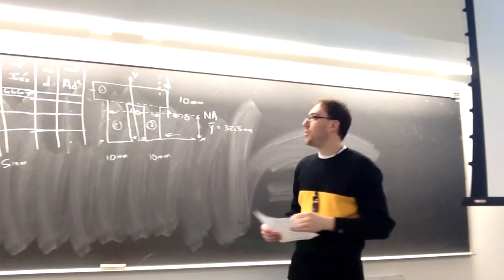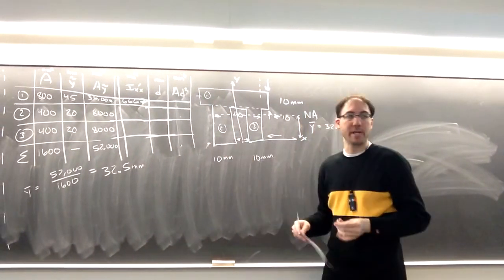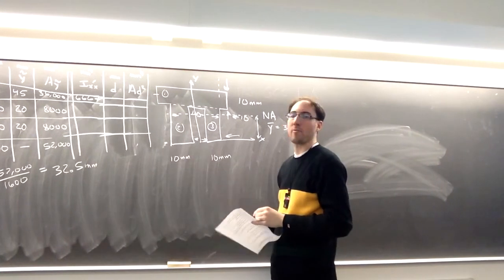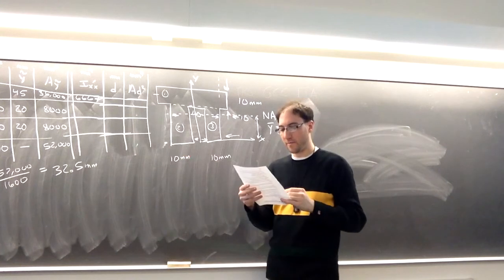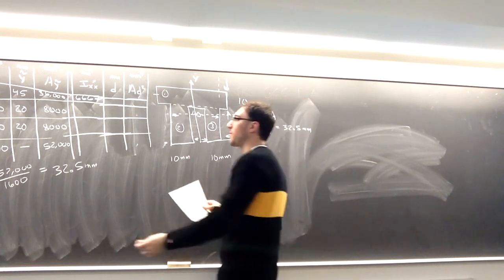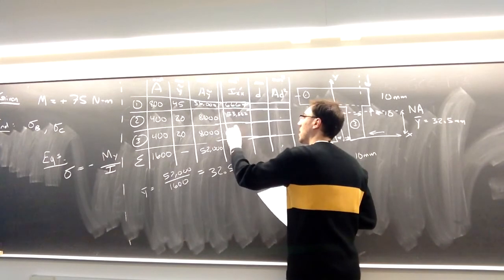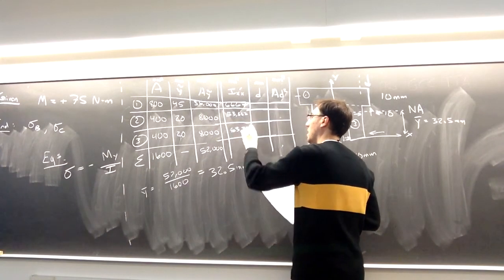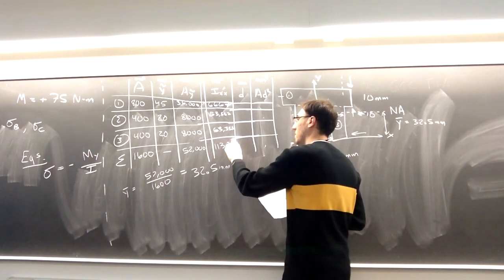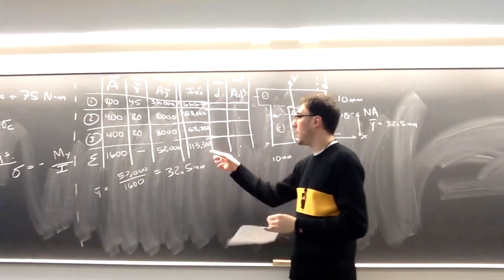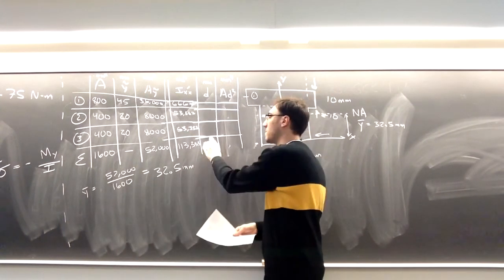For shape number 2, again, it's the vertical dimension that's going to be cubed. So for shapes 2 and 3, it will be 40 cubed times 10 over 12. So that'll be roughly 53,333. So the total, adding the three shapes together, is 113,333.